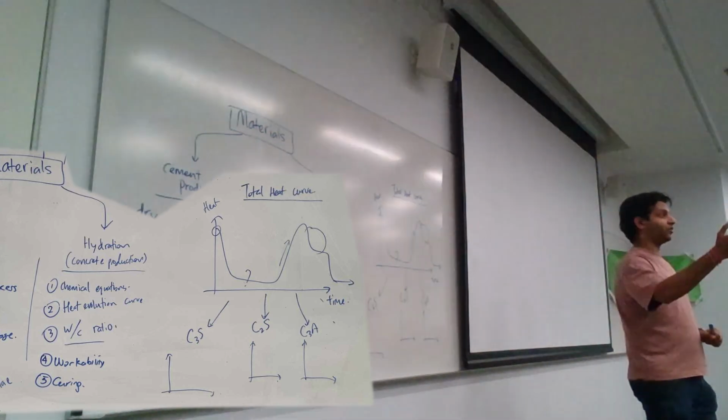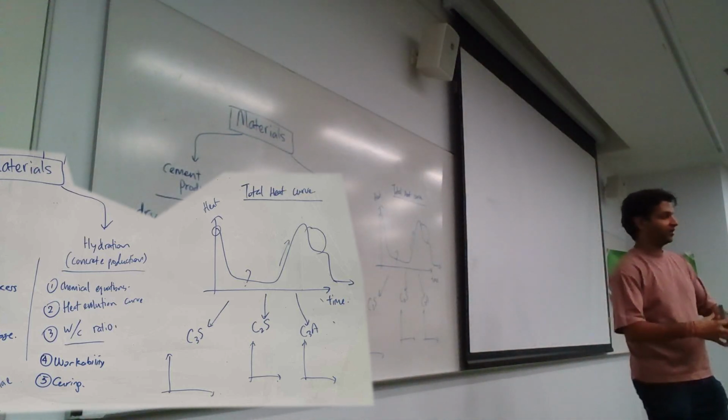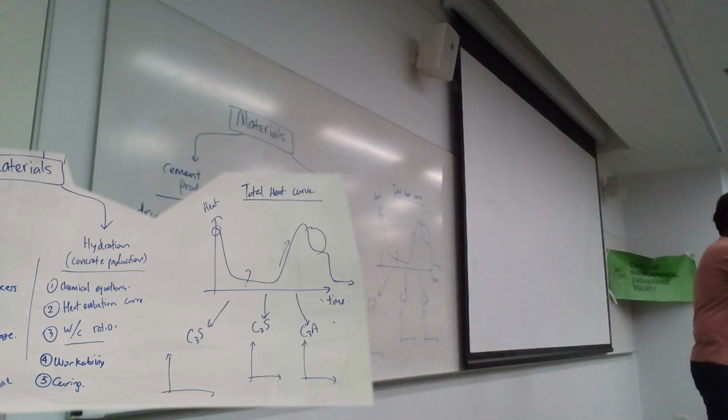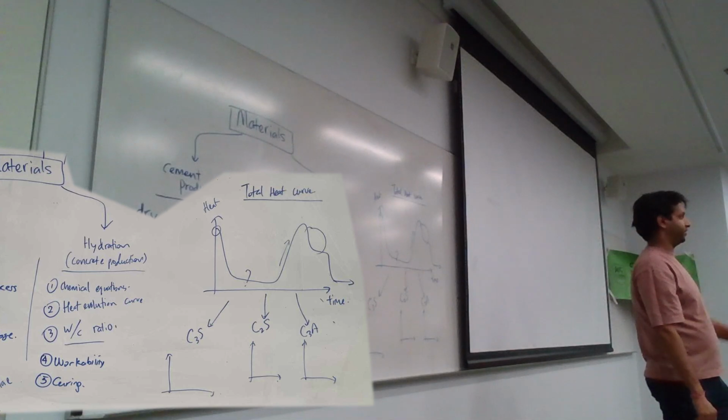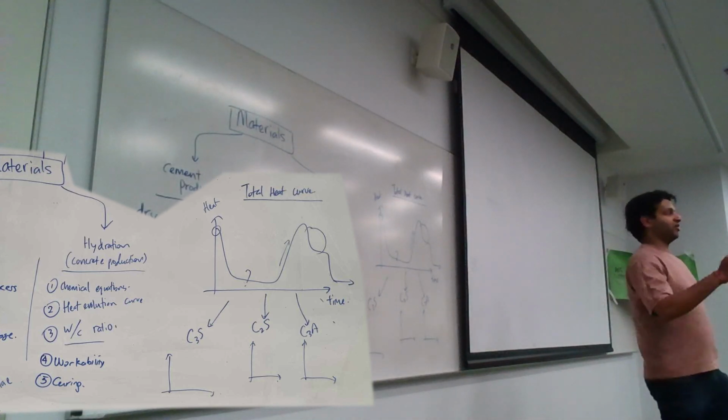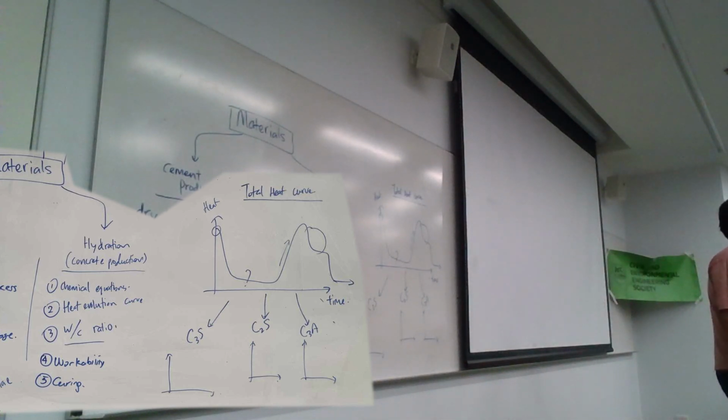But when you're curing your concrete, so we say you mix in your concrete, it's all mixed in inside, and now it's set, and now you're curing it, so you're spraying it down with water. If you spray it down continuously with water, does the strength decrease over time? No, it actually increases.